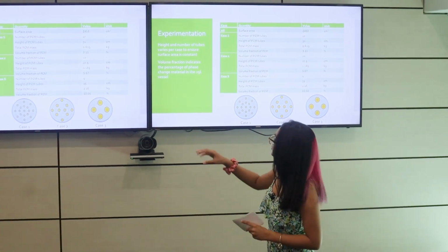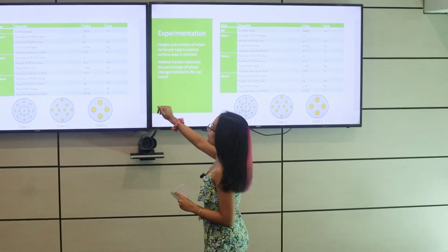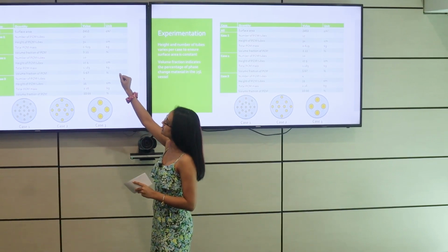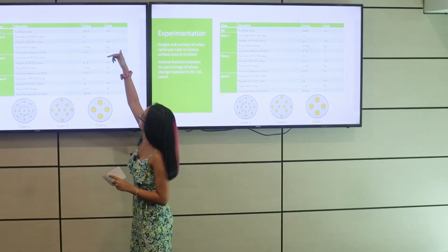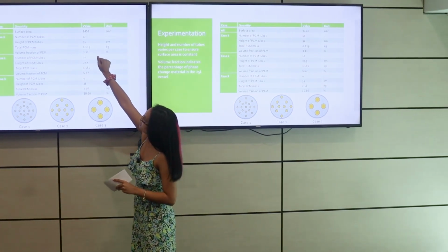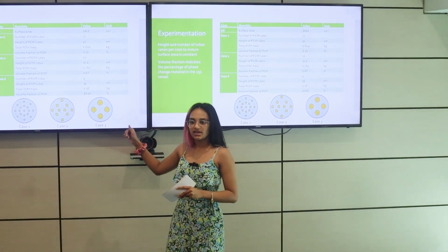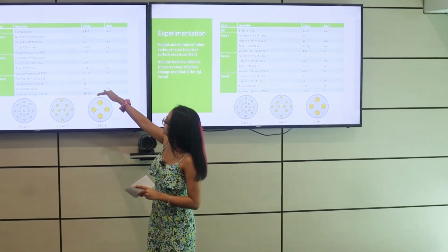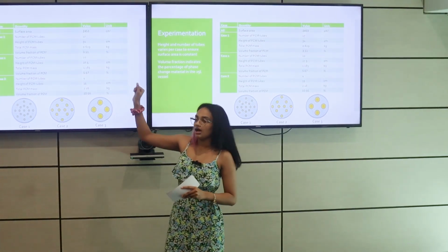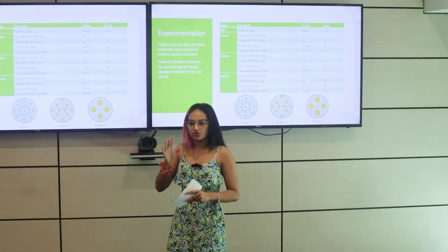So just to explain what I've shown in this table here, these were my 3 cases. My first case was the smallest pipes that I used, which were 15 millimeters. And as you can see here, the number of pipes also varies: it's 4 for case 3, 10 for case 2, and 17 for case 1. This was so that I could keep the surface area constant between those 3 cases, and also vary the amount of wax. This volume fraction of wax is the amount of wax per case divided by the total amount of water, so total volume.